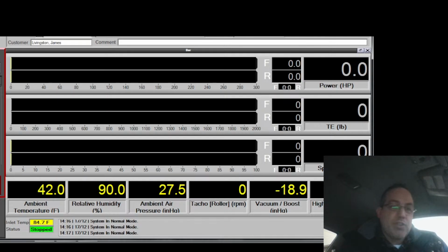They change their software, so they might have different axes. So I'm looking at the X2 data, and at this same pulse width here, it's pulling a lot more than I'm pulling right now with this data. So my low pulse width stuff might be wrong. I might actually have X2s in here, and it's tuned for regulars because it seems like it's really rich right now. So I'm going to try that.